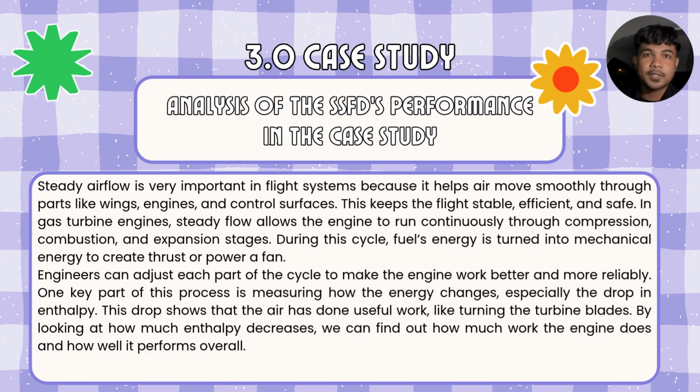A key part of this process is monitoring energy changes, especially the drop in enthalpy, which indicates that the air has done useful work, such as turning the turbine blades. By measuring how much the enthalpy decreases, we can determine the engine's work output and overall efficiency.